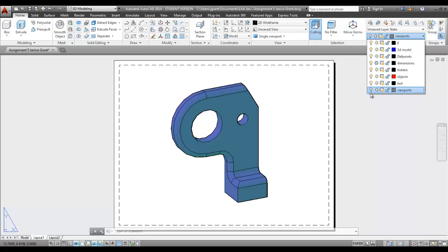And also, if you turn the layers off in a bigger drawing, AutoCAD is still regenerating those objects. If you freeze the layer, then it helps to improve your drafting time, because those objects that are frozen are ignored during the regen time. Okay, so little sidetrack there.